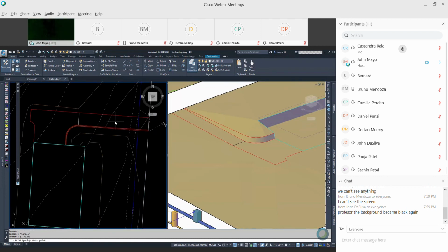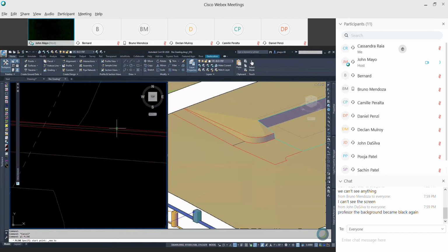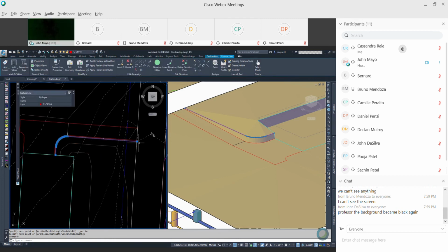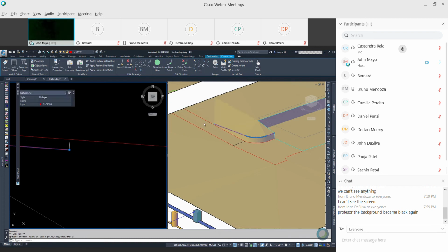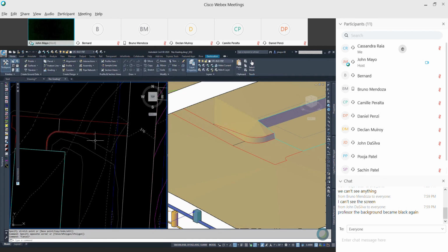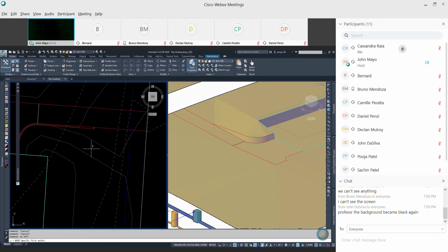I can draw a polyline anywhere along, starting at the bottom, go perpendicular, and that polyline has a constant elevation. So if I just grip at it, this top of wall to that polyline, we can see how we reduce that wall length. And I told you, check your contours. If you're closer than 6 feet horizontally, then you're greater than that 1-on-3. I've got 8 feet there. I'm not.